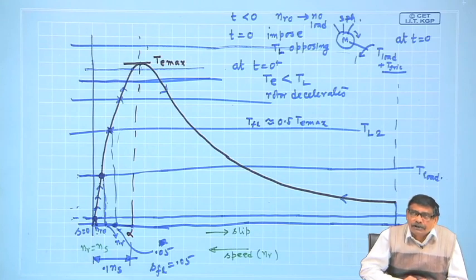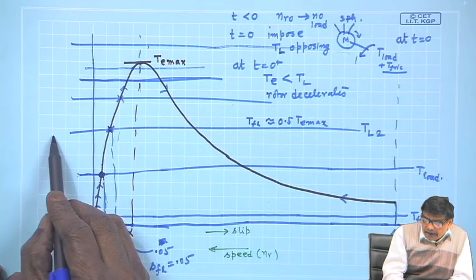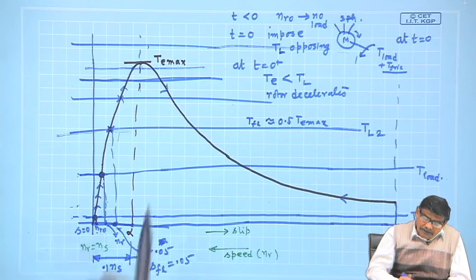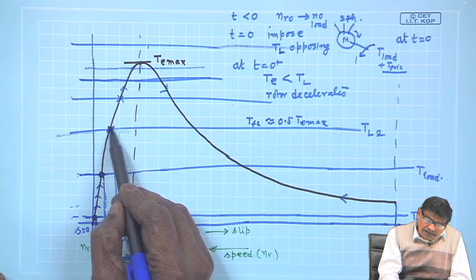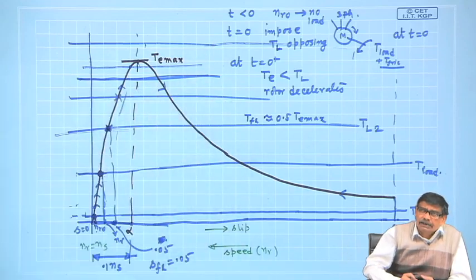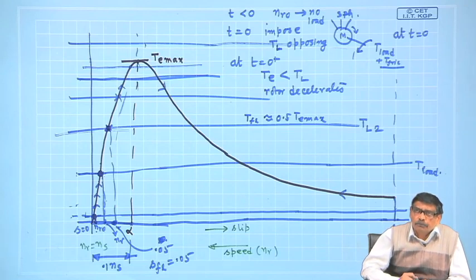That is why, keeping all these things in mind, the full load operating point of an induction motor is decided somewhere midway between these two. It can be a bit this way or that way, 4% full load slip is also possible, you will see motors, but it will be of that order, 4%, 5%, 6%, that is the typical value of full load slip of a 3-phase induction motor.